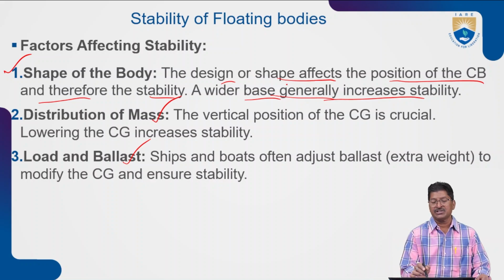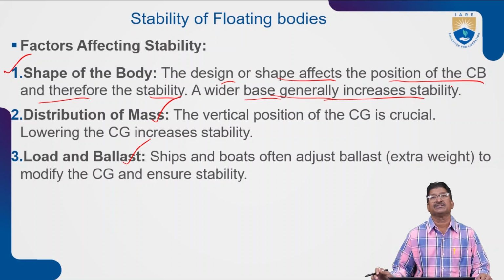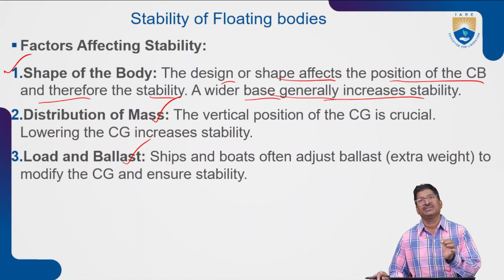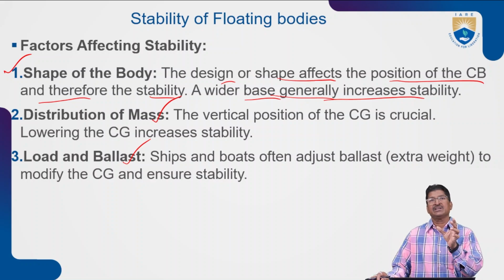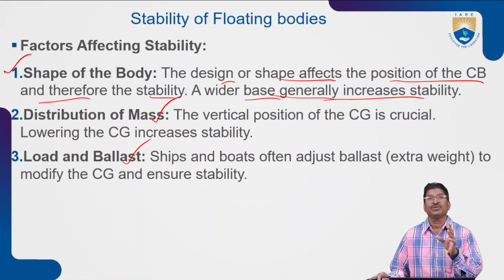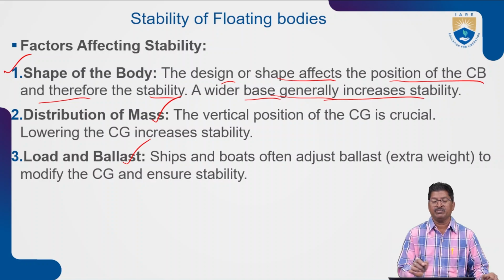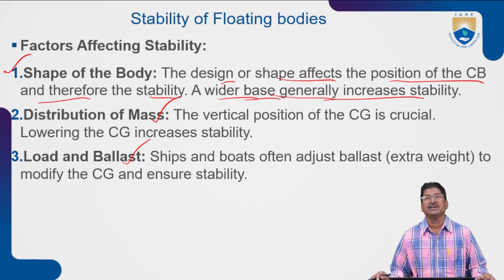So design or shape affects the position of CB. CB means the center of buoyancy. The center of buoyancy will change depending upon the shape of the body. The center of buoyancy should act above the center of gravity of the object. So with a broader, wider base, it will generally be stable.